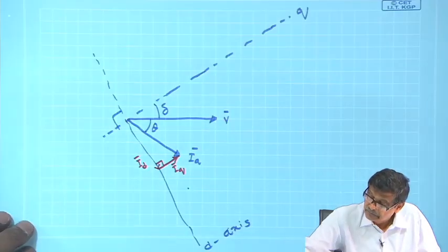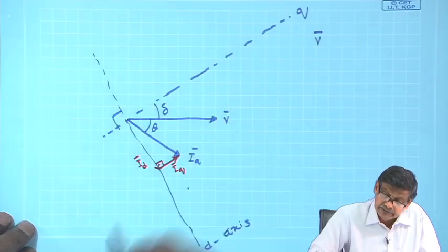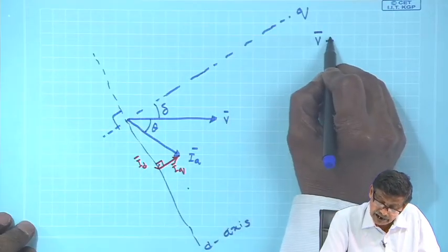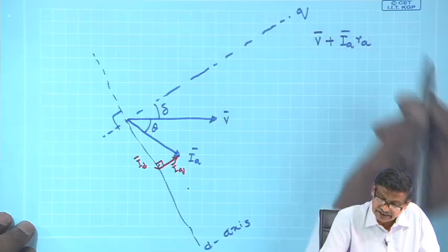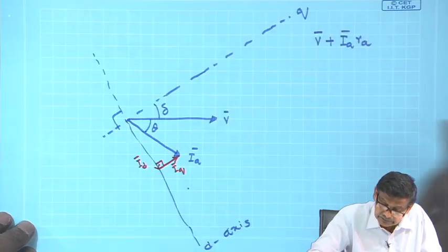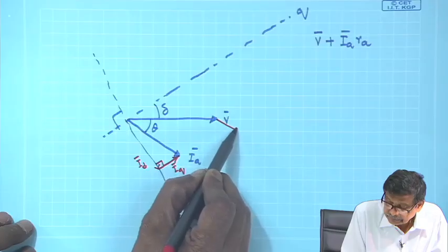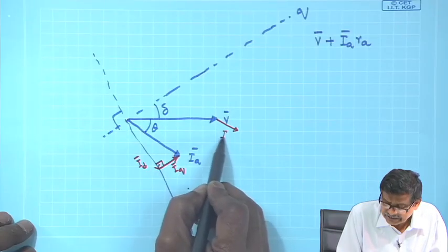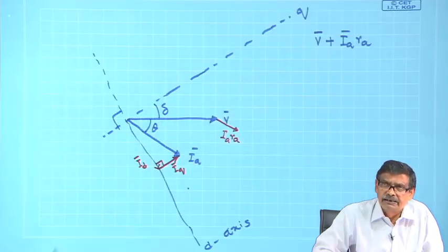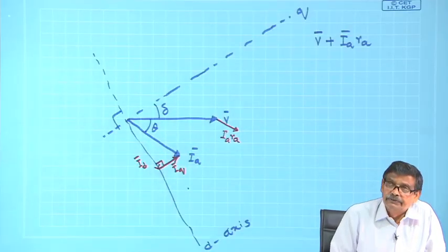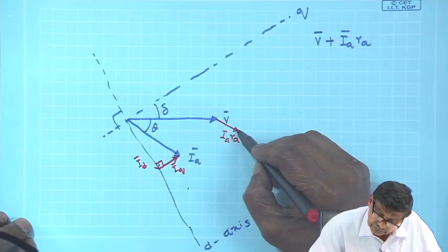Then to your terminal voltage V, you add I A R A, of course, I A R A remains I A R A. So, I will add I A R A here. There is no dq axis, you need not break it up. Of course, you can do I d R d and so on. I A R A you sketch.